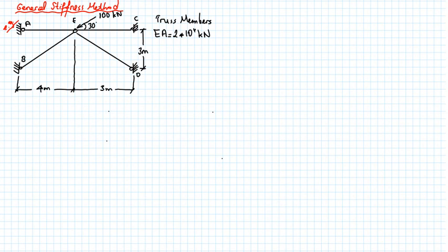It doesn't matter if you have a truss structure, a frame structure, or a combined structure. Again, we do discretization. The logic is always the same. Let's first simplify the structure. Member AE, so I have a node here, node E. Member EC, member EB, and member ED.